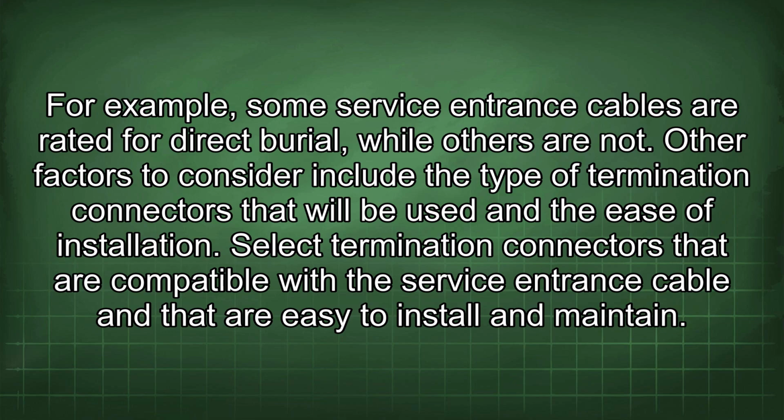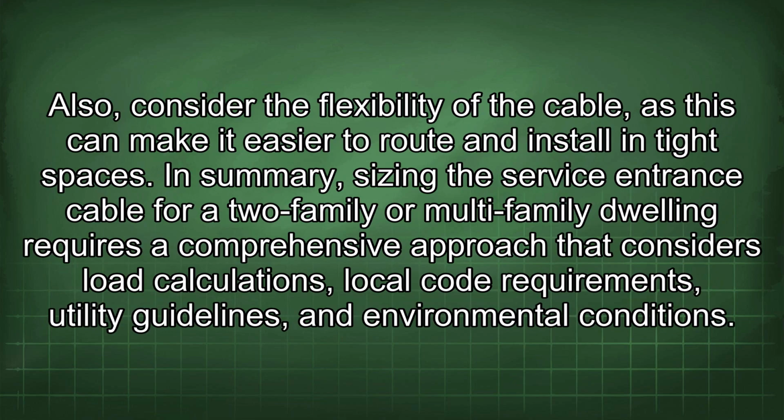Other factors to consider include the type of termination connectors that will be used and the ease of installation. Select termination connectors that are compatible with the service entrance cable and that are easy to install and maintain. Also, consider the flexibility of the cable, as this can make it easier to route and install in tight spaces.